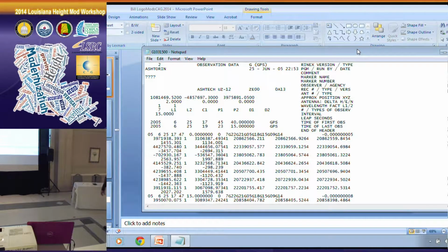We're looking at a RINEX file now. This is telling us what signals it used, 7 different signals. This is telling us the interval, 15 seconds. You can see here this is 2005, June 25th, 5:47:0 is the time. And this is telling us the satellites it read, which are those GPS satellites. If it had GLONASS, it'd have an R in front of them. This is just a text file, all right? So this is readily editable, and this is just the information.